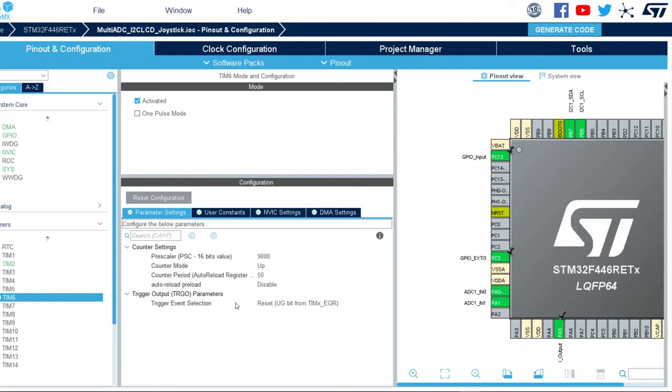I don't even know this, but buttons have a mechanical bounce whenever you press on them. The moment you press the button, it is really not stable for the first 1 to 5 milliseconds, so the state is not stable.